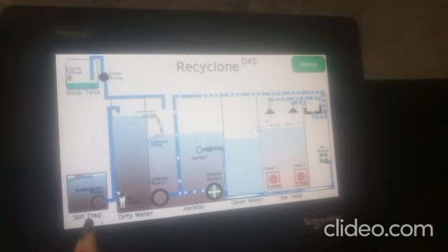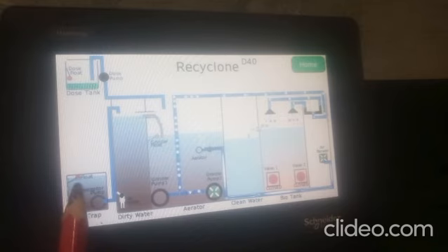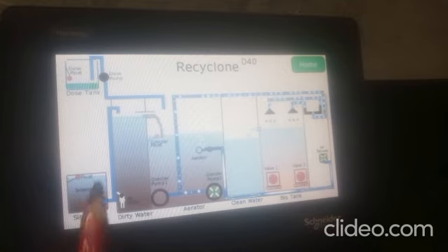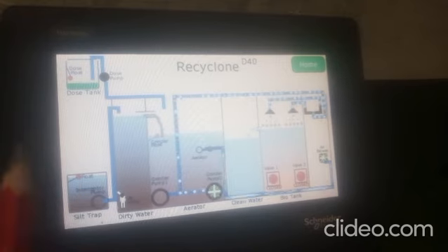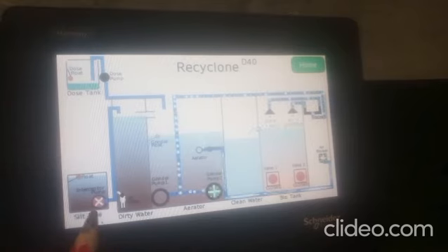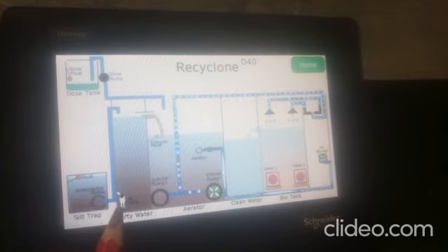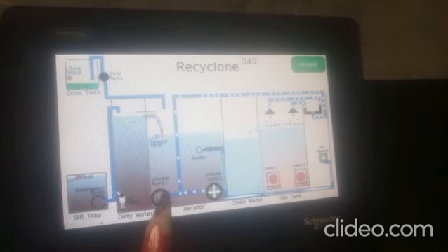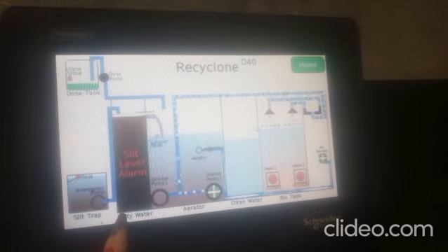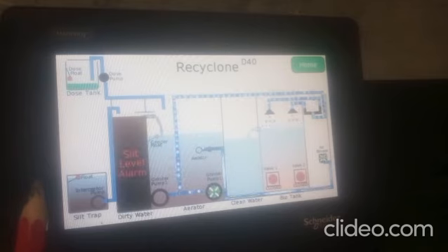In the silt trap, we have our interceptor pump and our interceptor float. When the interceptor float is low, it will show the animation for the interceptor pump running on, and if the interceptor has tripped out, there will be this animation. In the dirty water tank, we have our silt probe and our overflow into the aerator tank. In the event that the silt probe detects too high a silt, this alarm will indicate. This is also visible on the main screen.